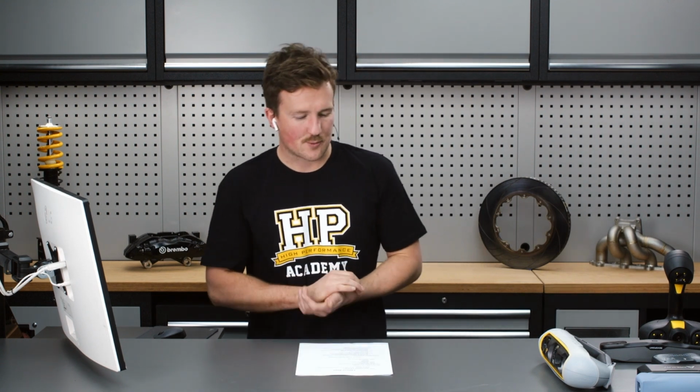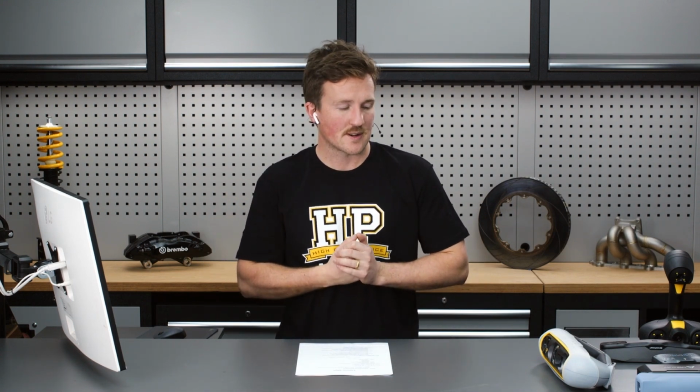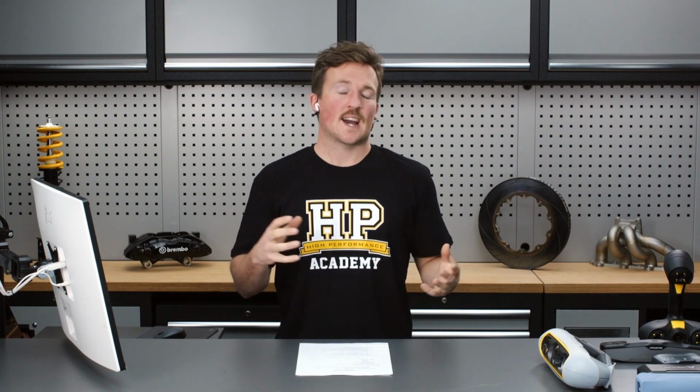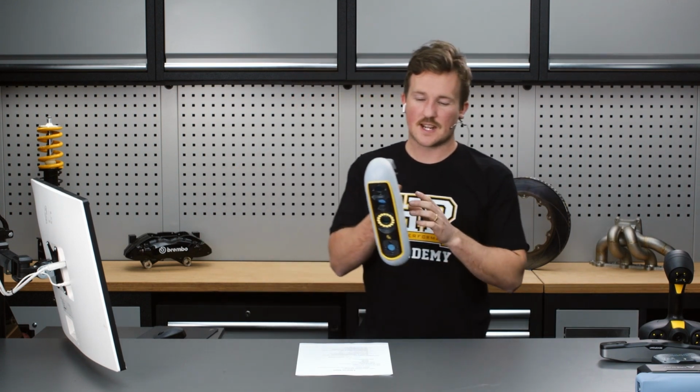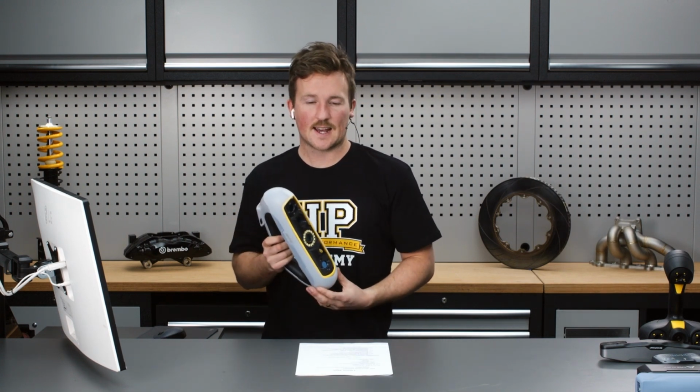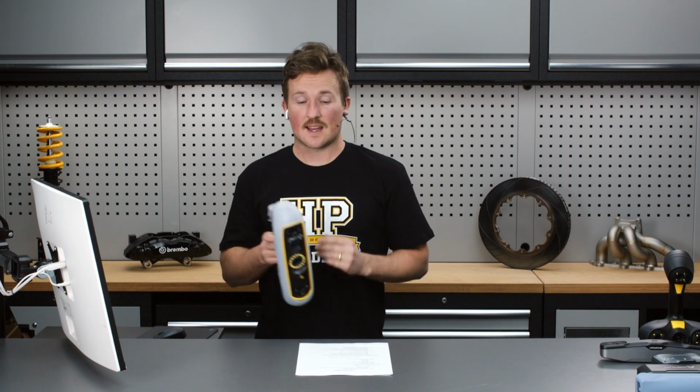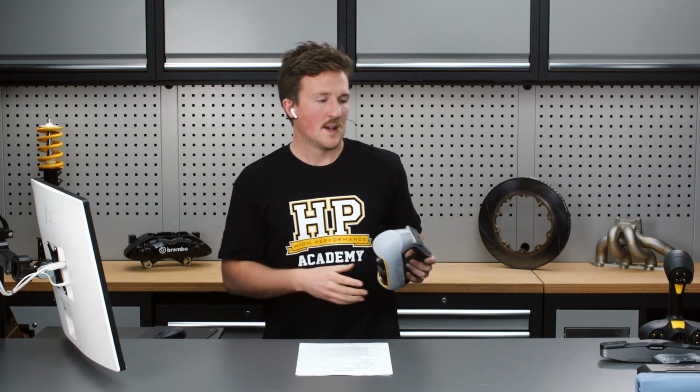So we touched on this briefly before when we were talking about the coordinate measuring machine, something like a FaroArm, for example, and that's the tracking of the scan. As we have the scanner and we're moving around the object, the scanner needs to continuously understand its position relative to the object, or the object's position relative to the scanner. And it does that via tracking, and it tracks different features.